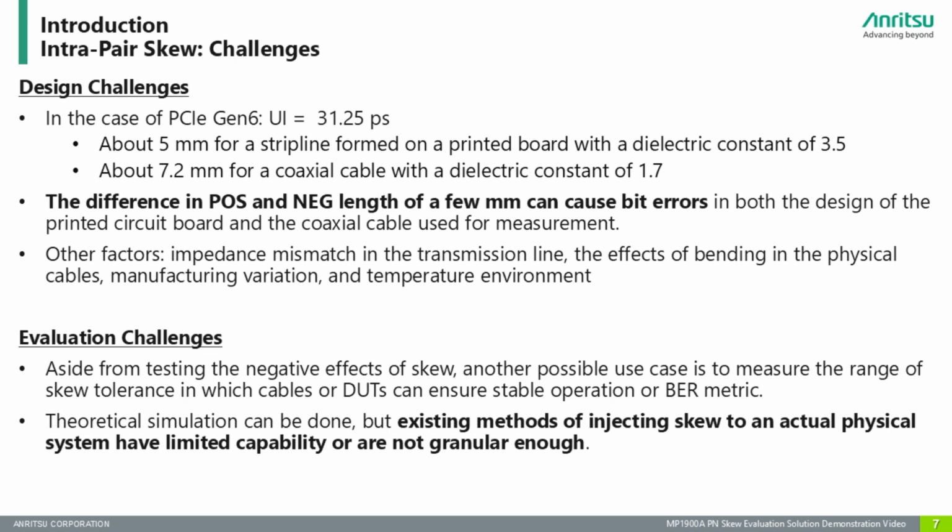As for evaluation, aside from testing the negative effects of skew, another use case is to measure the range of skew tolerance in cables or DUTs. Even with the importance of considering skew, evaluation challenges still remain. Theoretical simulation can be done, but existing methods of injecting skew to an actual physical system have limited capability or are not granular enough.